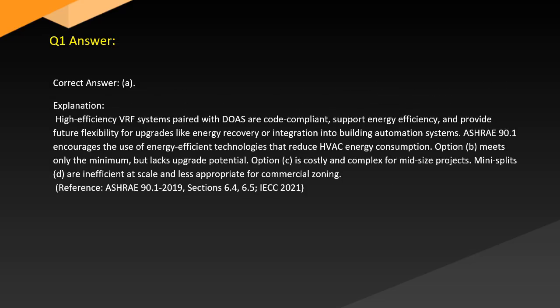Answer. Correct answer: A. Explanation. High-efficiency VRF systems paired with DOAS are code-compliant, support energy efficiency, and provide future flexibility for upgrades like energy recovery or integration into building automation systems. ASHRAE 90.1 encourages the use of energy-efficient technologies that reduce HVAC energy consumption.